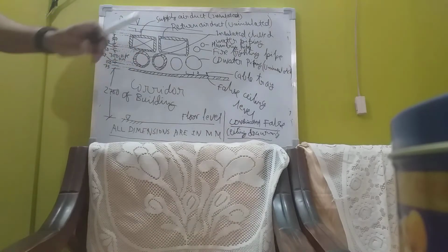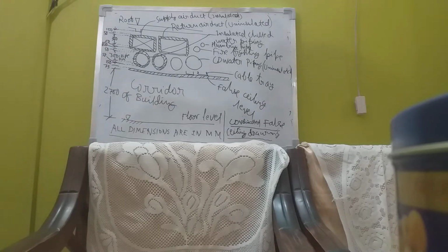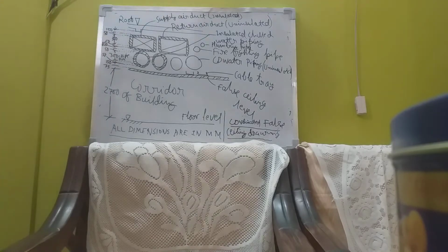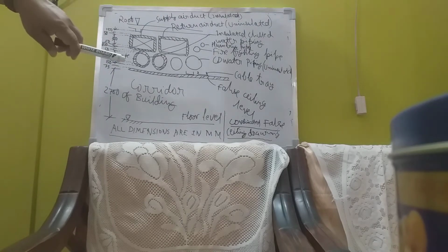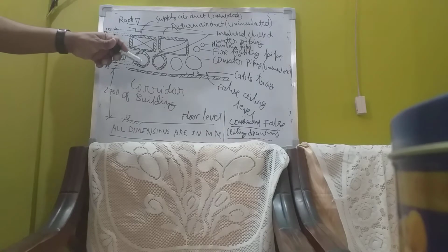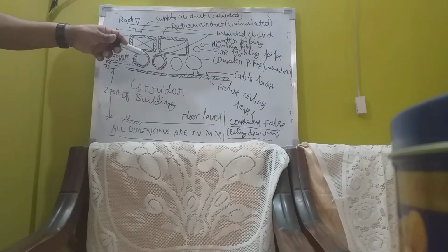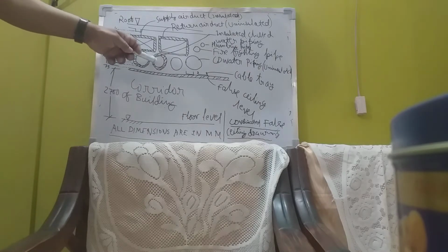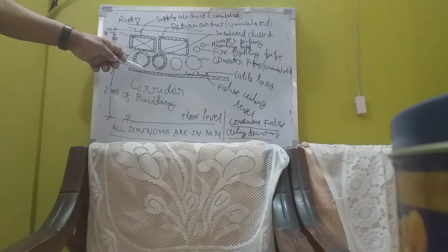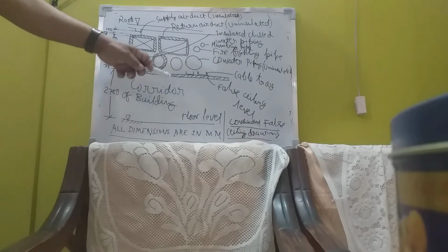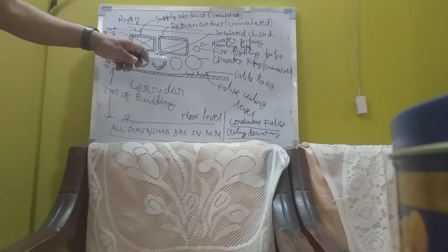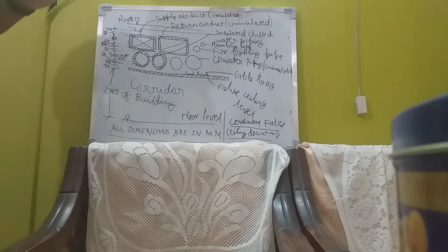But the chilled water pipe requires insulation because it passes chilled water from the chilling machine, which is at very low temperature. The insulation is provided outside. One reason is that there is no heat loss from the chilled water. The second reason is that there is no condensate formation on the outside. There is a chance of condensate forming outside, and if it forms, it will drop through the false ceiling, the whole false ceiling will be wet and the whole structure will be gone. So, to save that, insulation is provided on the chilled water pipe. This insulation is generally 50 mm thick.